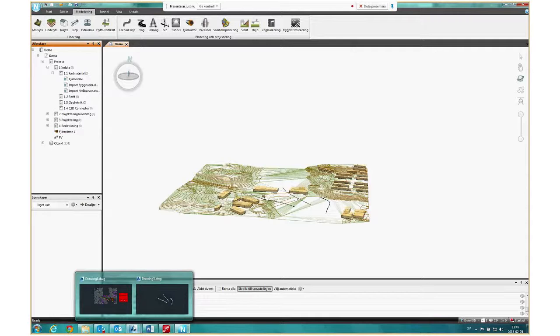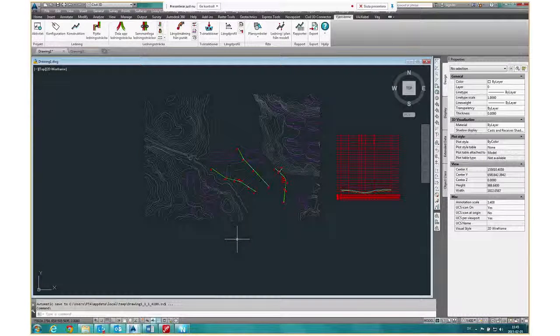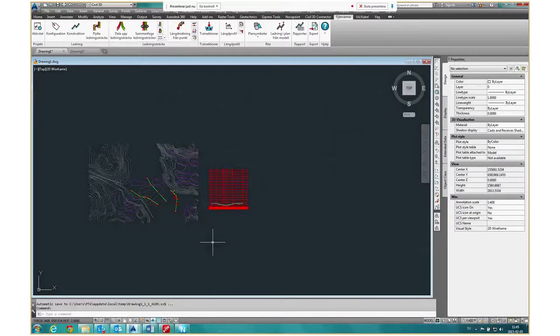So, as I understand, to create drawings, I still need to use the standard procedures of Civil 3D. I mean, I need to create a drawing set in Civil 3D. You're not related to drawing creation. You're just related to creation of geometry. Yeah, you don't need Civil 3D, but you need a full version of AutoCAD to create drawings.